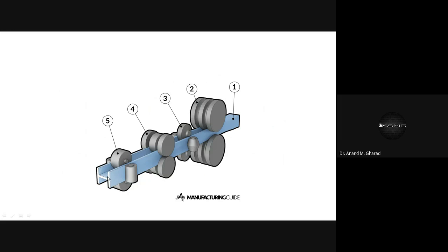And thirdly, there may be distortion that may be observed in the cross sections. Reason, because as you can see, this is still in the hot state. And then, after giving a particular shape to this mold, what will happen? It is allowed to cool. All of a sudden, it is allowed to cool.